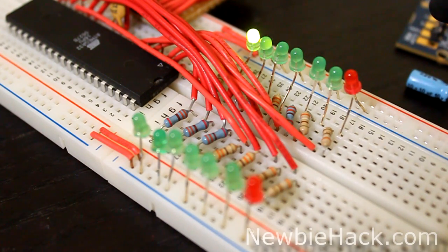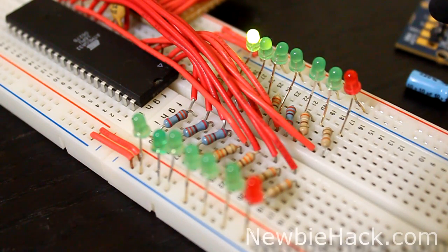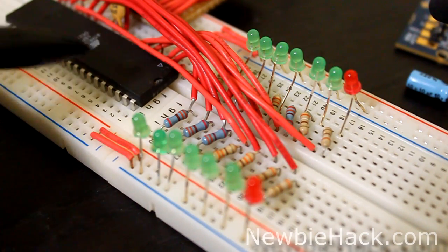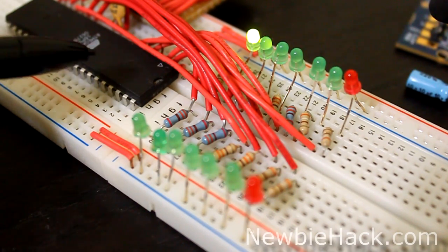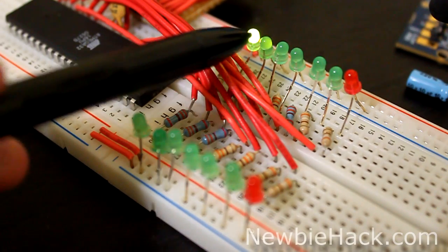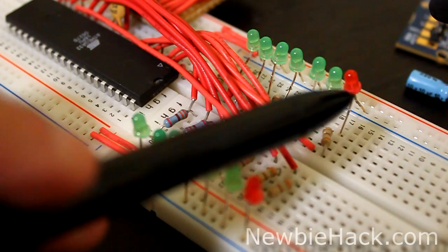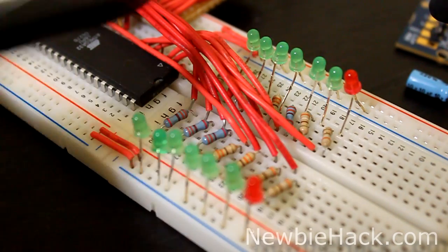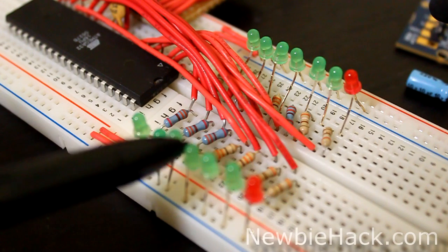Although, if you try to time this, you will be 10% off either direction or maybe right on, because the internal clock is not that accurate. So there you go, you have an LED blinking every second. Now let's do the chasing of these LEDs. Seventh of a second, and then these LEDs will chase every second.